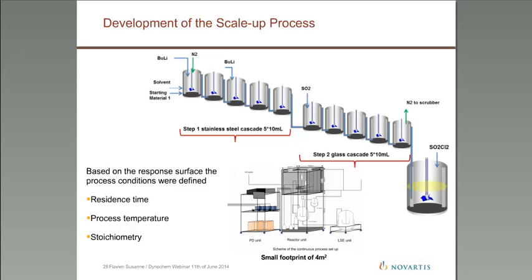And that material directly overflows into a stop and flow system where we add by portion SO2Cl2 to do the chlorination. We had all this system together, with the pump, the reactor, and the transfer line, within a 2x2 meter footprint. So really, really small.